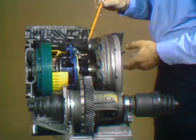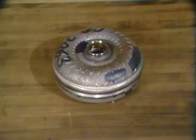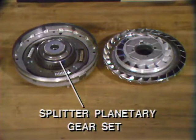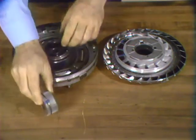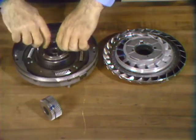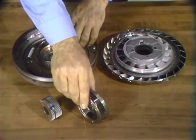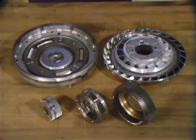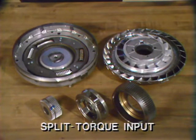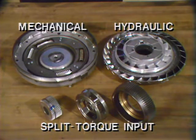The ATX resembles other Ford 3-speed automatics in many ways, but there are important differences. First, in the torque converter, we have a splitter planetary gear set, which is installed between the converter cover and the turbine. It consists of a sun gear, a planetary carrier, and a ring gear. This gear set allows the main gear train to have a split torque input of hydraulic drive from the turbine and mechanical drive from the converter cover.